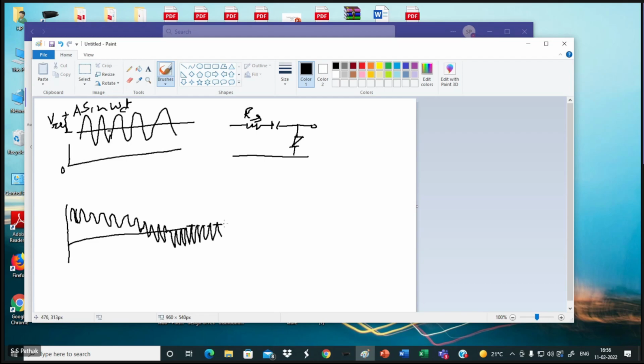So what is this voltage to this voltage? Here to here is your 2A. This is your 0, and this one would be minus 2A. So it is clamped. After this transient response is over, it is clamped in steady state, or you can say the DC has been totally blocked.